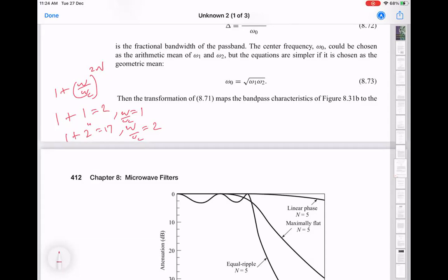So that's why this kind of stuff is often called filter roll-off, right? How fast the attenuation increases. It's often given in dB per octave. The language comes from music, because as you go from one octave to the next octave, I don't know for the musicians here, if you go from sa to the next higher sa, the frequency gets doubled. So an octave in frequency means a doubling of frequency.